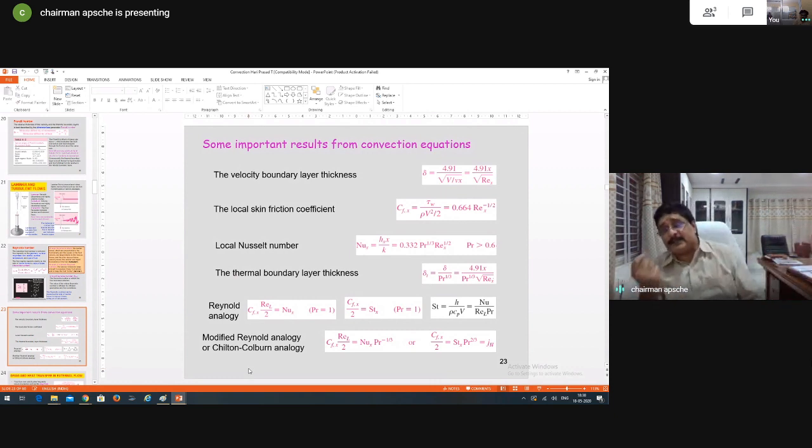See, by just knowing one number value, you can really understand what nature of fluid flow is taking place there. Right? Prandtl number. So just now I have drawn the figures. Whether the hydrodynamic boundary layer is more, or the thermal boundary layer is more, or whether heat influences are felt to a greater y distance, or viscous influences are felt to a greater distance, you can know simply by knowing the value of Prandtl number.